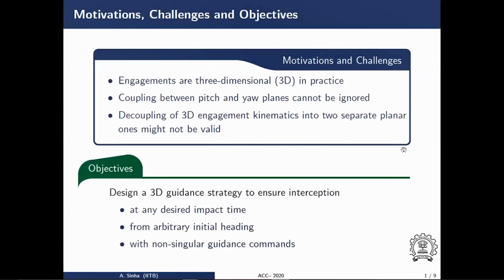In the existing literature on 3D guidance, the strategies were designed by decoupling the 3D engagement geometry into two separate two-dimensional ones. However, one simply cannot decouple the 3D engagement into two separate planar ones if the coupling between the planes is prominent, as this could lead to adverse effect on the guidance performance.